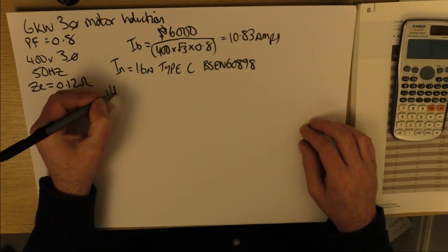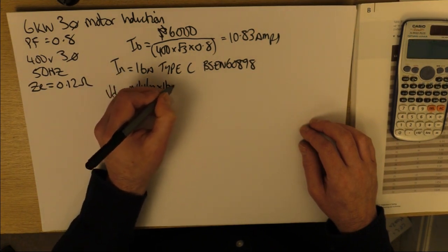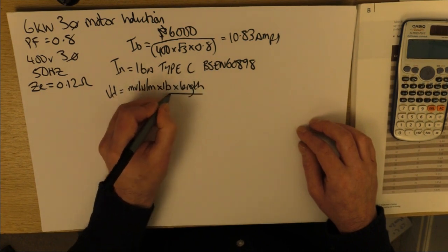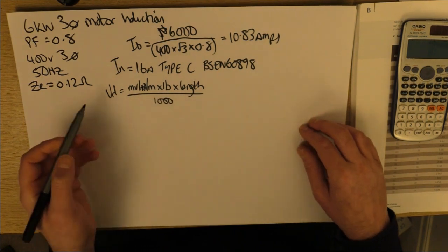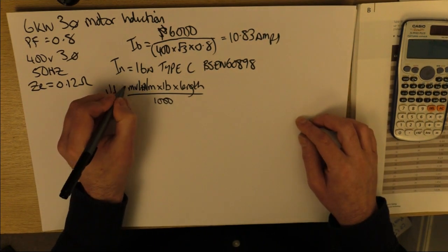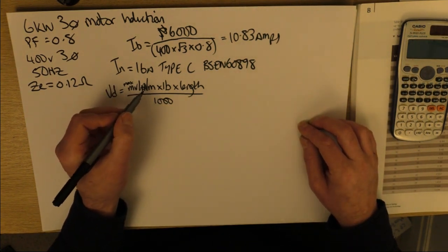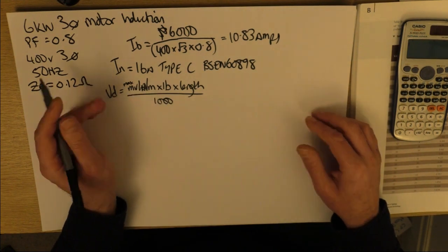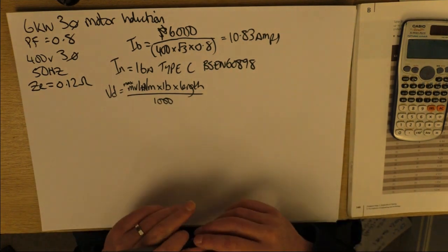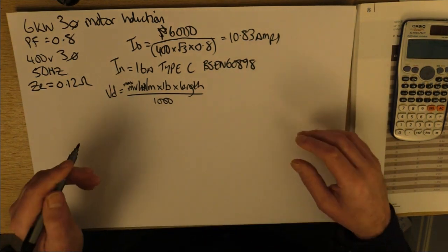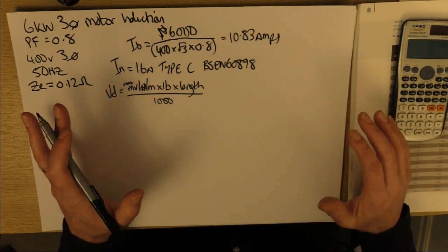We're going to check out that volt drop equation first. What we're going to do is flip it on its head, to transpose for this. What that gives us is a maximum millivolt per amp per meter value, and then we go straight to that table and choose a cable based on that. Sometimes you get it right, sometimes it doesn't work. We still need to check it for current carrying capacity, which obviously we'll do next. So it's just the other way around really, but we're still checking for the same stuff.